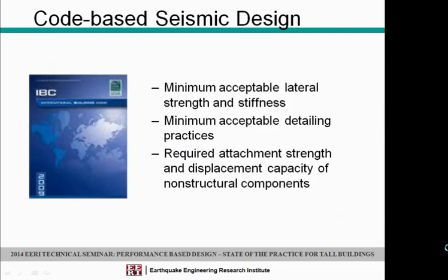It very rigorously specifies how we have to detail our buildings: how the reinforcing steel has to be bent and placed in concrete elements, how we weld pieces of steel together with thickness ratios of elements of steel, how many hold-down type devices we have to put on a wood shear wall building. All of that is carefully regulated in terms of detailing.